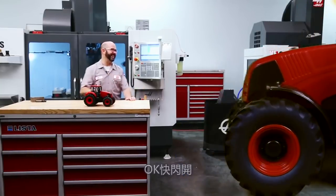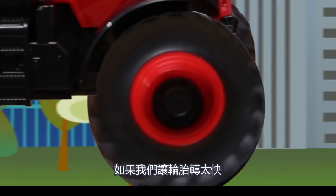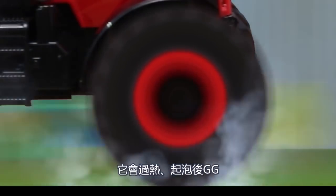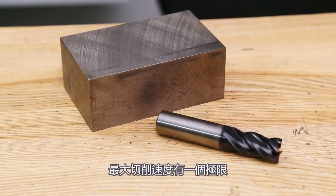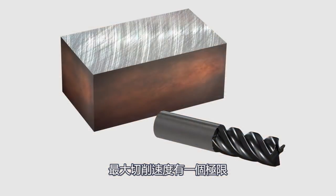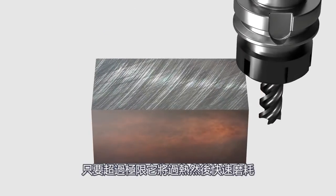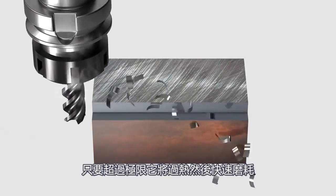Okay, back it up, get out of here. If we were to run our tires too fast, too many surface meters per minute, they would overheat, blister, and fail. Our end mills work in the same way. There's a limit, a maximum cutting speed that a specific tool can go on a specific material. Any faster, and it begins to overheat and quickly wears out.